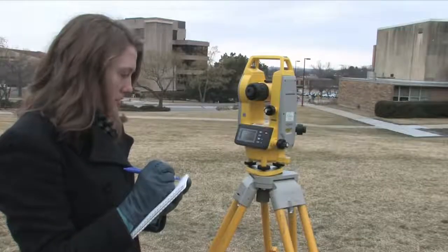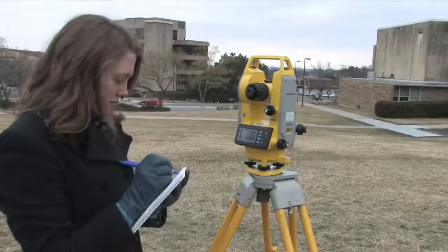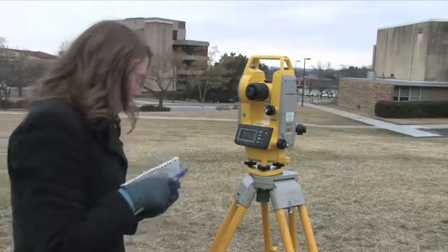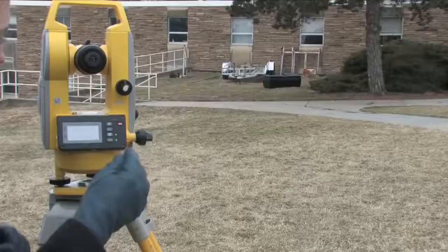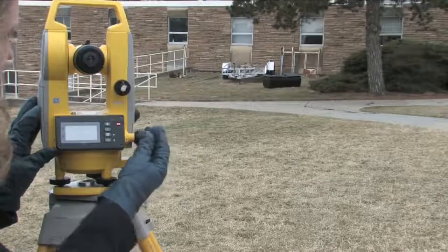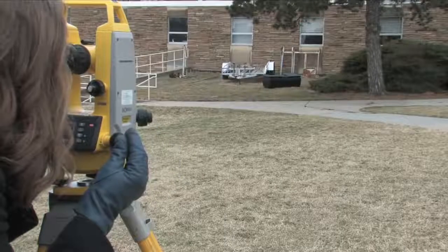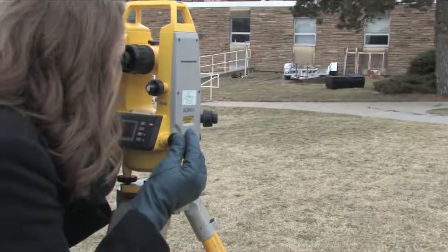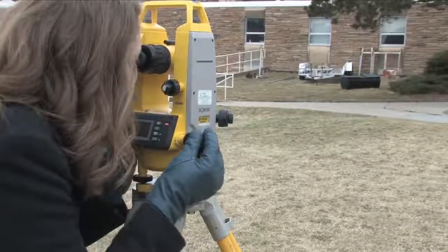The upper stadia reading minus the lower stadia reading is your S value for point A. Also record the vertical angle shown on the instrument. Next, we will proceed to turn the angle to the right by unlocking the horizontal and vertical locks and then rotating the scope to be directed towards the rod at point B.